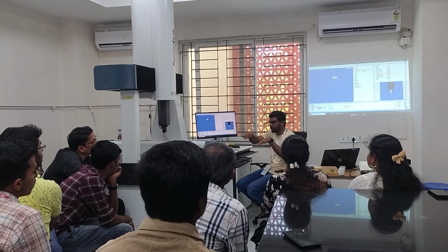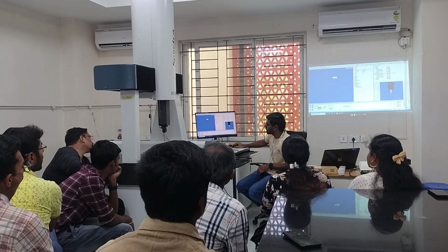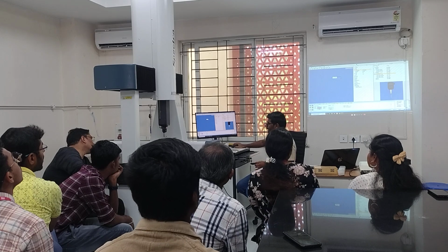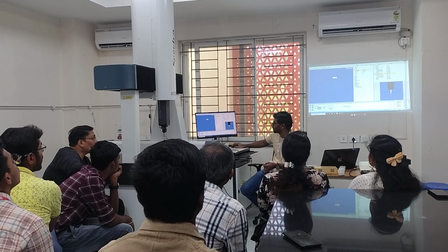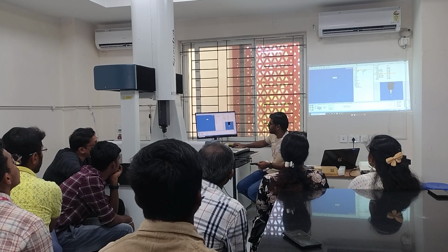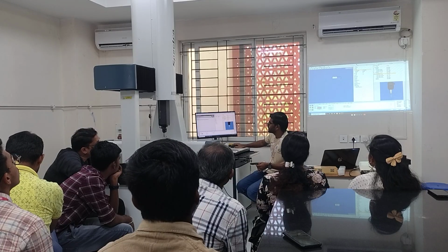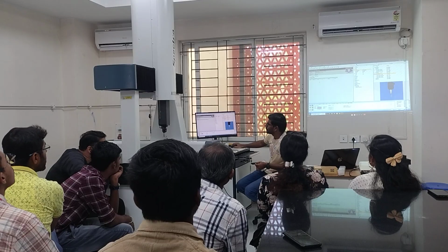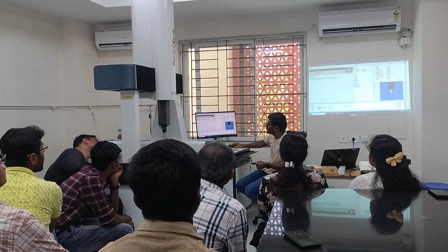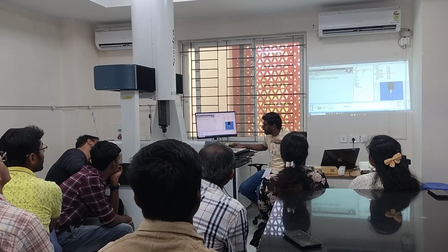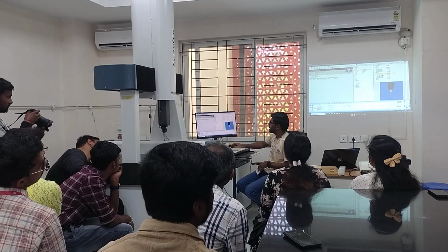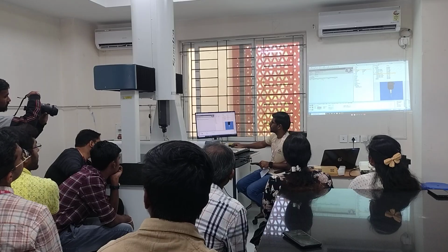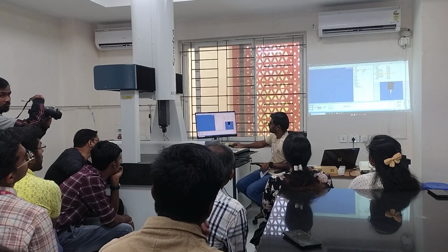No, because it will be comparing all the points with itself. So flatness here comes out as 0.01296. So that is the flatness we have got. If I click on accept, it will show in our report. So this is how our report is going to come out. For the top plane, if it is perfectly flat, it should be 0, and now it is not perfectly flat, therefore the deviation is 0.0130.